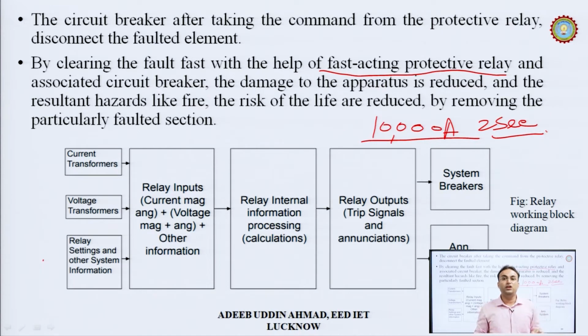including your TV or refrigerator or some other equipment, if this fault is transferred into the distribution part. Also, this high current can damage the transformer, the isolator, the bus bar. So, this current has some high value. That is why we are going to eliminate it, we are going to reduce it.